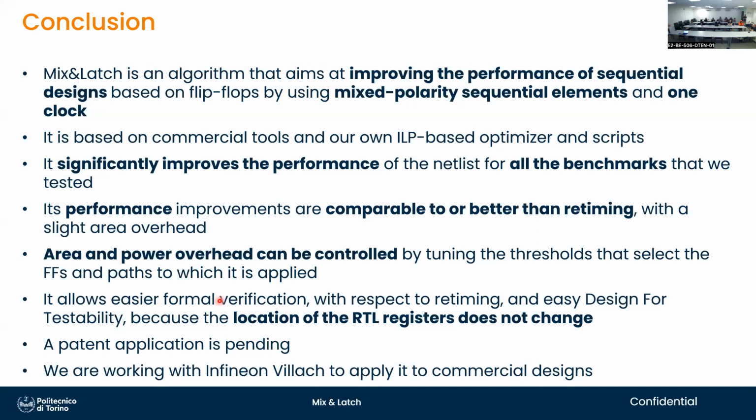It's people who don't know how to design with them in the first place. People don't frequently mix latches and flip-flops in RTL designs. Sometimes they do, particularly at the boundary of the circuit when you deal with analog and so on, or when you want to optimize a long-distance communication. At that point, you might use those techniques for a few latches in the entire circuit, but not on a massive scale like we can do now.